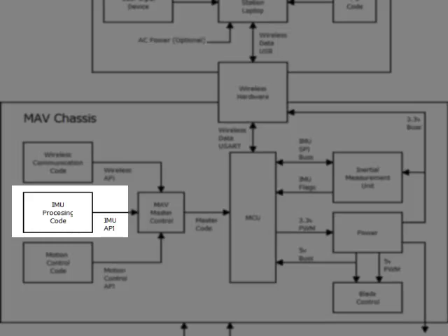This algorithm takes in the signals, filters out noise, and combines the linear accelerations and rotational velocities from the sensors in order to come up with an overall better guesstimate of the orientation of the craft, much better than can be achieved through more rudimentary techniques.